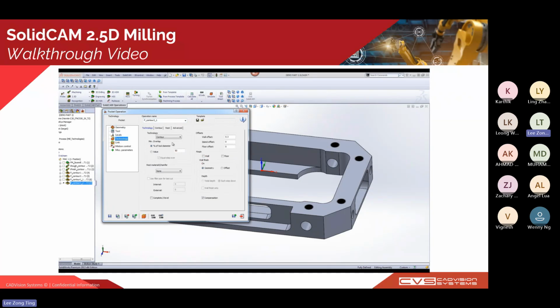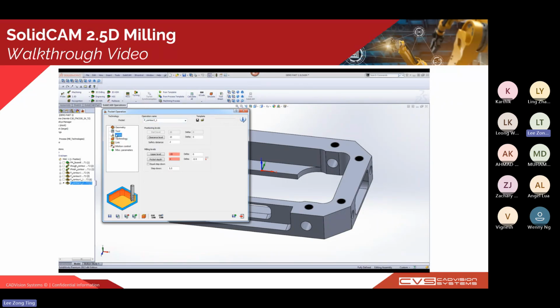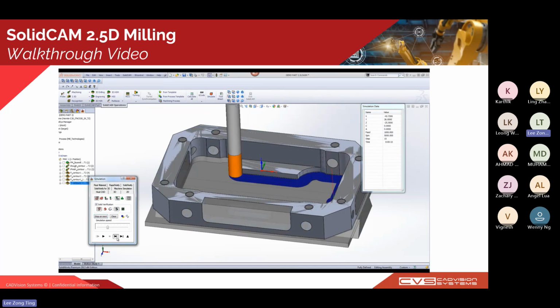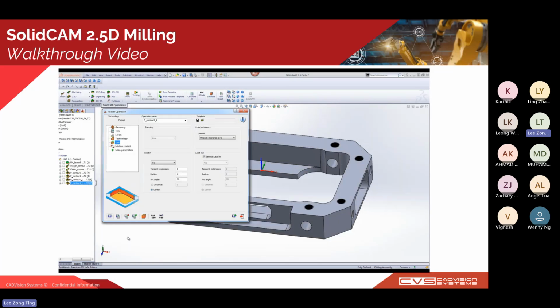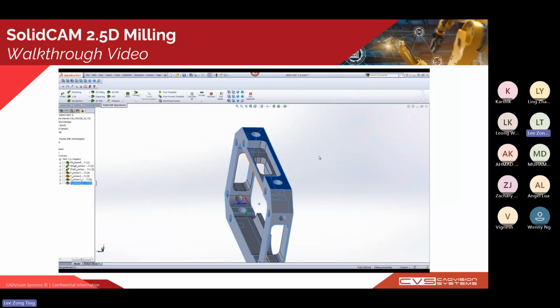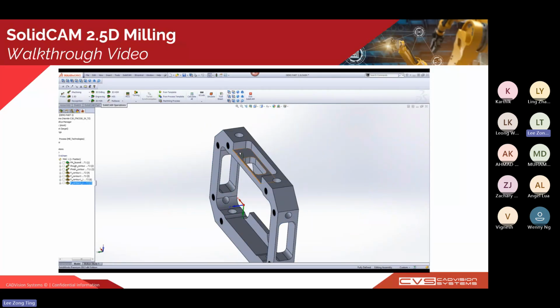Then I change the technology to rest material and, using the same parameters, remove those offsets, and simulate it again. You can see that it is able to automatically compute the rest material left by the previous operations. So you can eliminate those air cuts in your machinings.